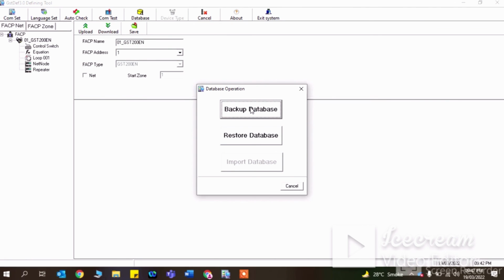In those scenarios, you can do it from the panel, where there is an option called system. It will ask for the password. You need to give the password as 24220011 and click enter, and there is an option called initialize. If you click initialize, there will be a third option, wipe memory or initialize the panel.